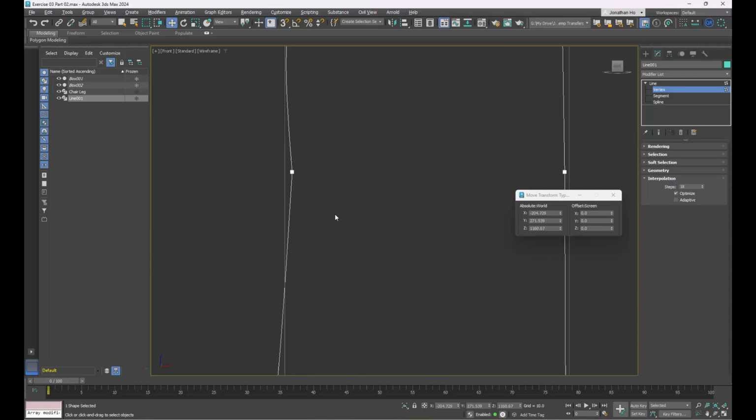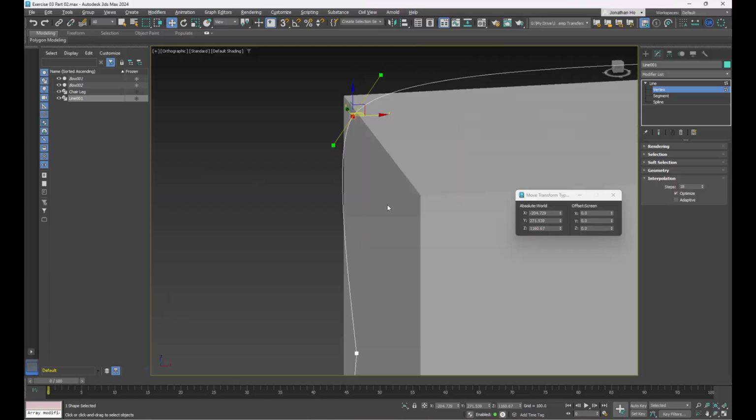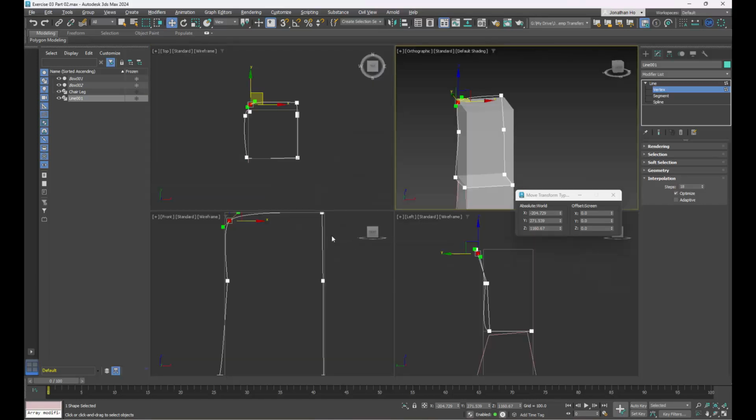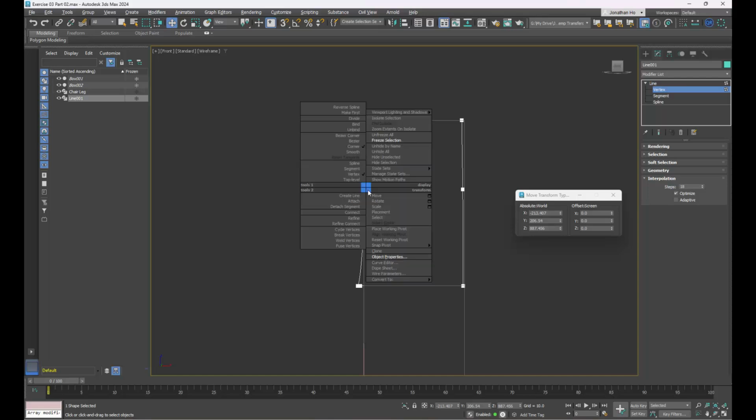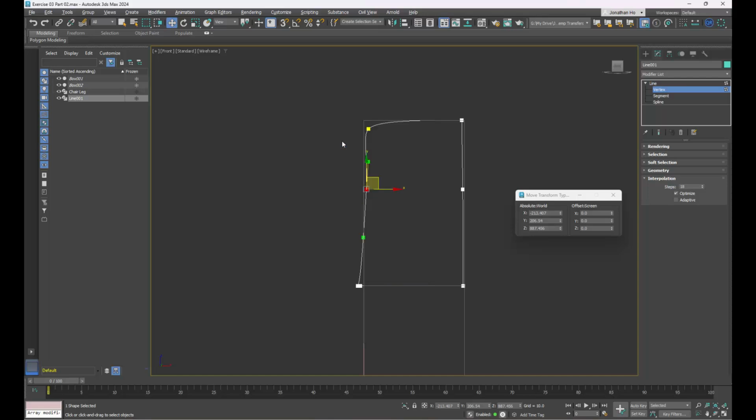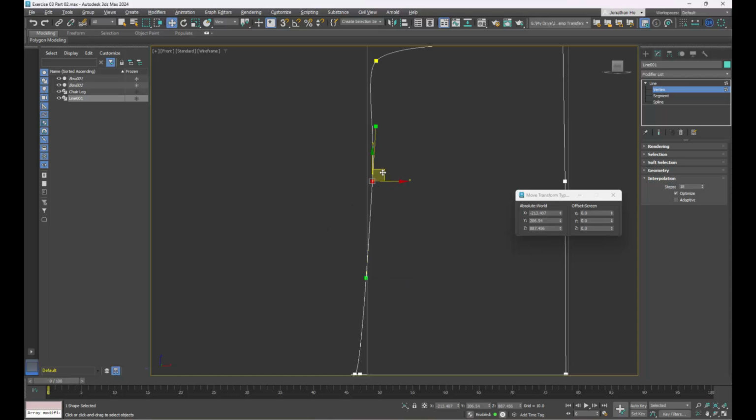All right, and then when this is done, we would then be able to do next the other one, the backing itself, right? So I'm going to select this vertex again, and right click to change it to Bezier again. And then once we change it to Bezier, we can now tweak the curvature itself of the chair.